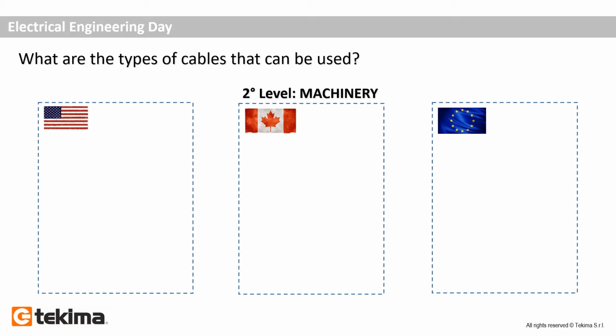For the machinery in USA, when I choose our wiring methods, again, I have to define which type of cable is needed. Two options in my pocket: AWM cable, recognized cable, and listed cable. So both are admitted in this case. It's mandatory to observe that AWM cables could be used for industrial machinery.